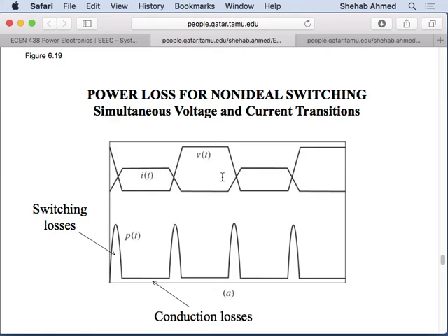So we have 4 components we're selecting in all the topologies: the switch, the diode, the capacitor and the inductor. Switch and diode is peak voltage, average current, both. Capacitor is peak voltage, RMS current ripple, I squared R still. Inductor is peak current or maximum current and I squared R as well, right? So both inductor and capacitor is I squared R because the capacitor has an ESR resistance and the inductor has the series resistance of the winding, right? So both of these are what's contributing to heat.